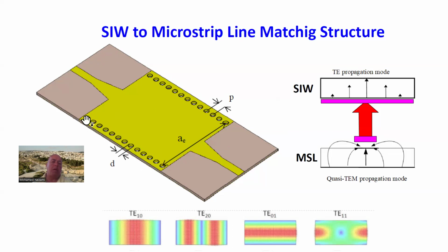Except in this case, we can't really plate the edges of this board; it would be costly and expensive. Plus, this waveguide would most times be in the middle of the board. So what we do is use what I would call a sampled electrical side wall with these vias.